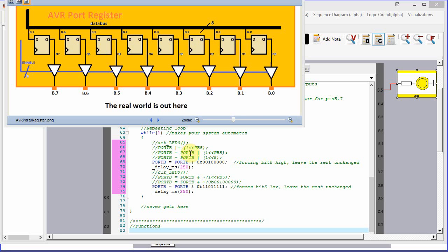At the moment, of course, all of these are enabled apart from B7, which is an input. So this is not enabled on B7 because B7 has got our little switch on it, but the rest of them are all enabled. The microcontroller bus, when it is active, of course, the signal's only clocked through when we want it to be clocked through, and then it only makes it to the output when we want to make it to the output. And we did that earlier in our program.